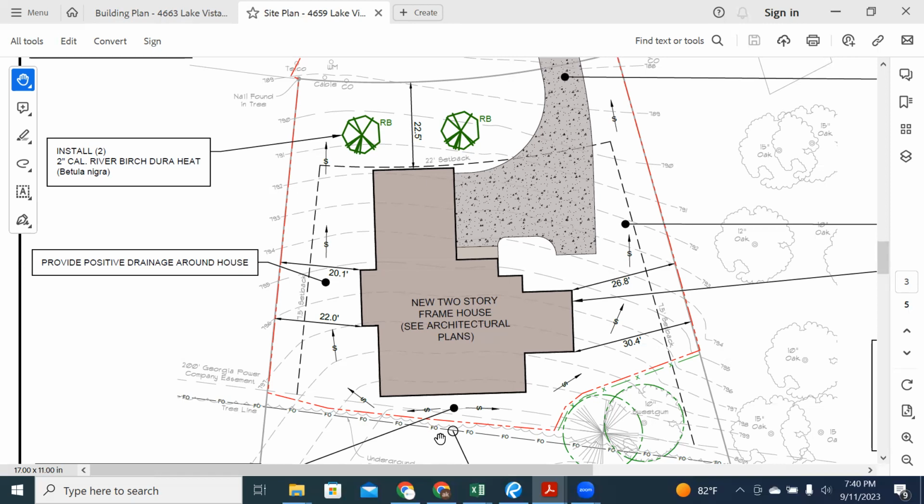So what I ended up doing is, while we were on site and the concrete guys were framing the outline of the house, I had them put a 10-foot by 8-foot patio back there. It'll go out 8 feet in depth and 10 feet wide. We formed all of that so that we can pour it one time.